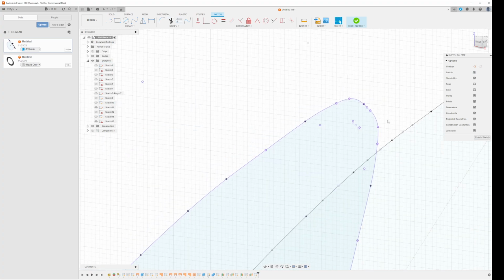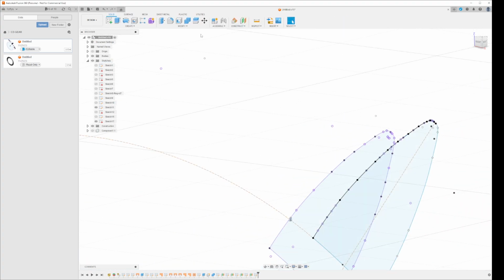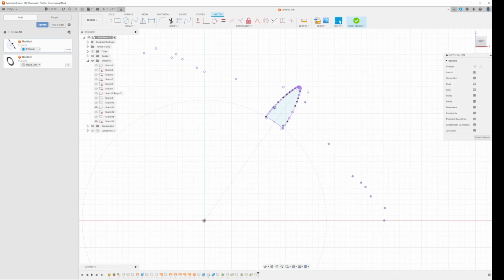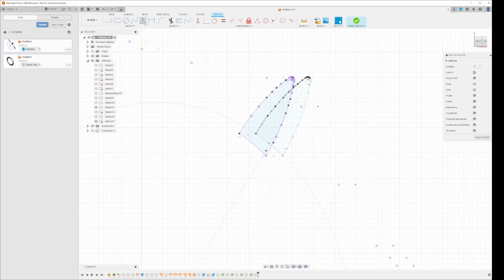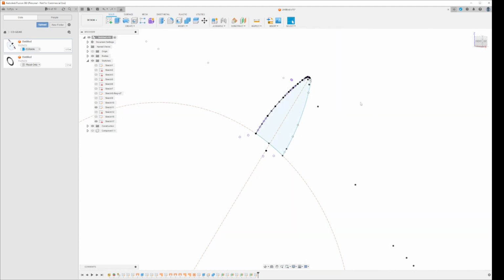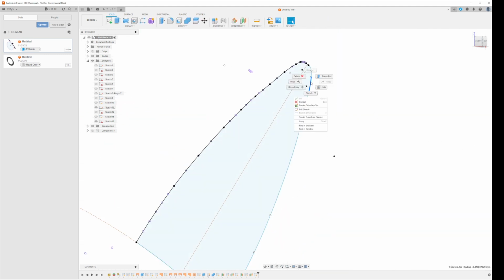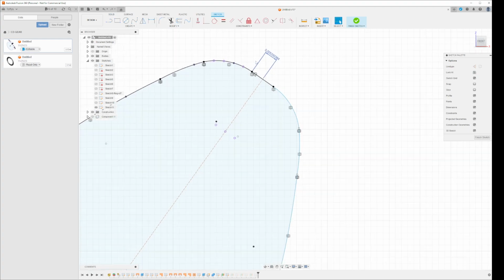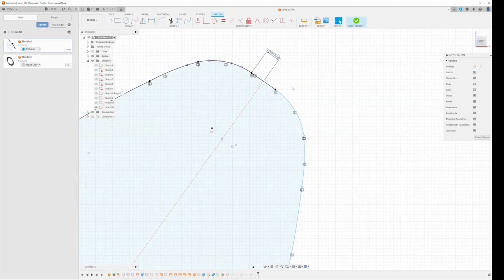So what I can do is go a little bit step back. So I can revert back to where I was here, and I can revert even further and say okay. So I go back to this and to edit sketch, and you see the reason this happened is because I used a mirror function. So I mirrored, I don't know if it was this side to this side or reversed, but here you have an overlap.